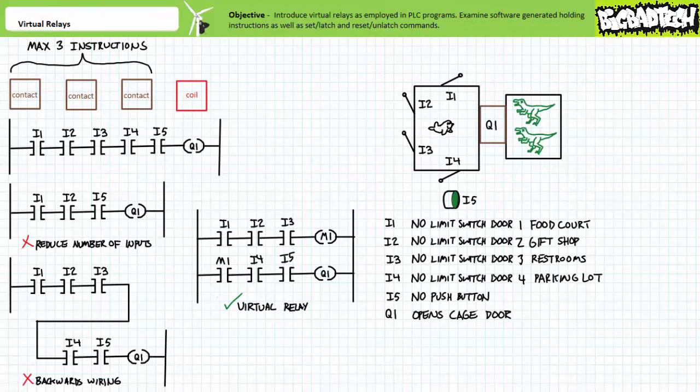A finite state machine, as the name implies, is a system that can be placed only in a limited number of states and needs to progress or regress through these states in a prescribed fashion based on the status of inputs and the current state. Used in this broader application, a virtual relay and its associated instructions can be used to signal when those conditions permitting entry to another state have been achieved, and if not, keep the system where it is, or bring it to another state.